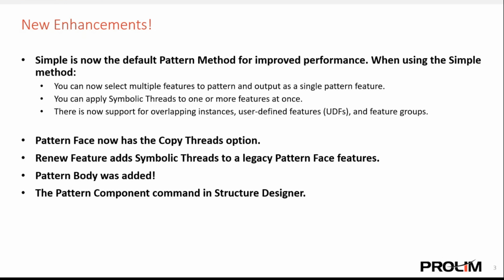On the pattern body side, you can use the pattern body command to create a pattern from a solid body that you select, and then combine the solid bodies in the pattern into a single body. After selecting a solid body to pattern, you can specify a reference point to determine the location for the pattern body. Select whether to create the pattern in a circular, linear, or helical layout. You can then specify different options to define each layout, such as the direction vector, rotation axis, and spacing. And I'll go over why you would want to use it over just your traditional Unite.